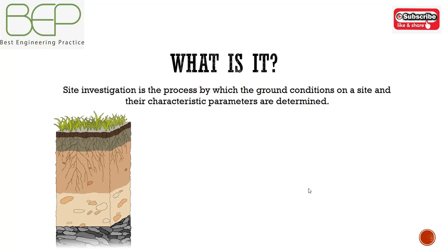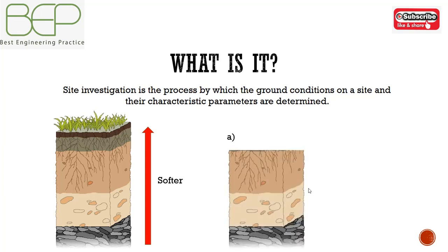Near surface soils tend to be softer, weaker and more variable than deep soil, and they therefore may require more extensive and more refined methods of site investigation than deep foundations. If the contractor is free to build a retaining structure by any method, then, for example, he might place the structure with a minimum of disturbance to existing soil.